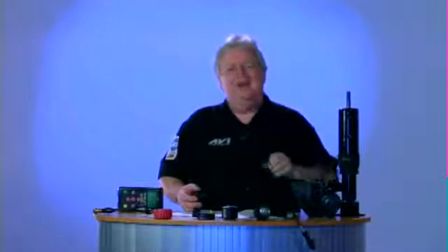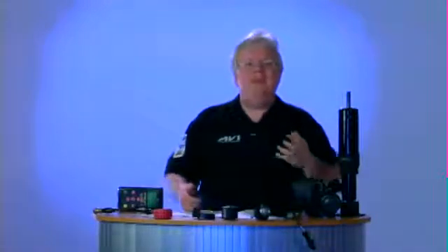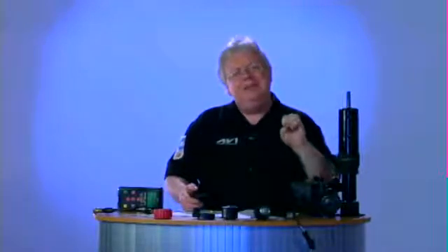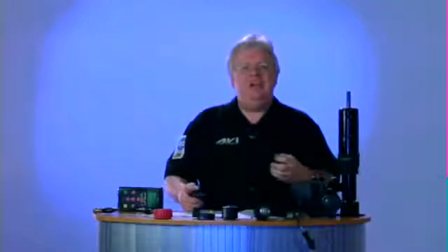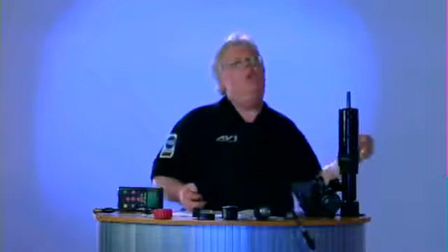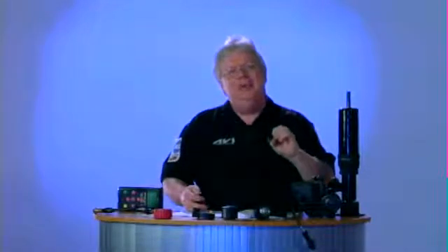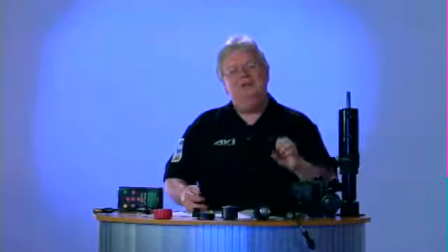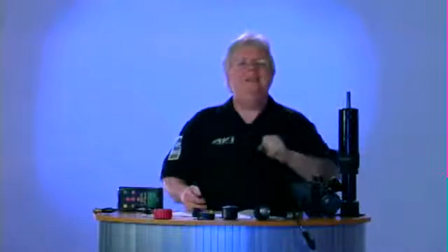Now, AirSept, the people who make primarily air conditioning tools and accessories, very niche type of repairs, they're making a filter that has a magnet on the inside of it. And according to one remanufacturer of steering racks, their warranty rates have gone way down significantly because this inline filter has been installed in the power steering hoses and is collecting the debris that normally would wreck a steering gearbox.